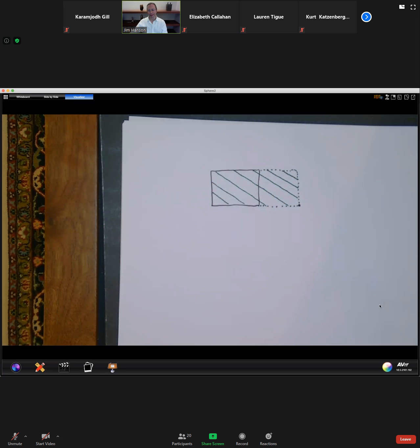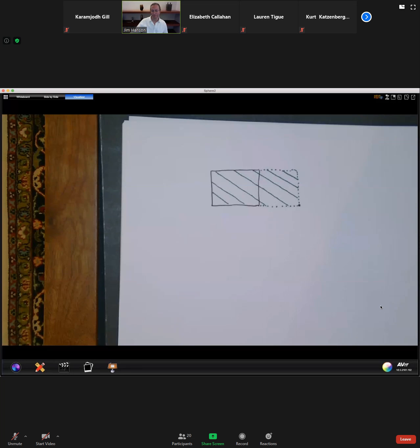Go back to this slide and show that the method, when you're making virtual little pieces of foundations, you're taking a summation of I. And there's no rule that says I has to be positive. So given that, does that provide any incentive here for a different approach? Can you find one I for the extended foundation and then subtract the piece that you extended?